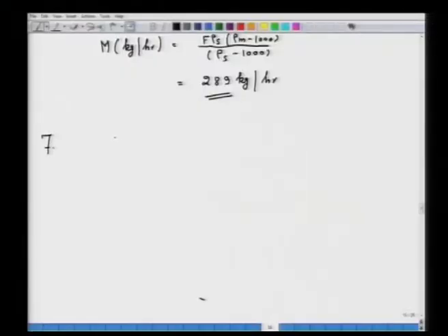So, here again I will proceed in my style, but I request all of you to please develop a new method of solution yourself. What I will be doing is first calculating the density of slurry in both these streams, and I will proceed that way. I have already given the formula for weight percent solid, the interconnection between weight percent solid and the densities, that is already known to you. So, I am straight away substituting those values.